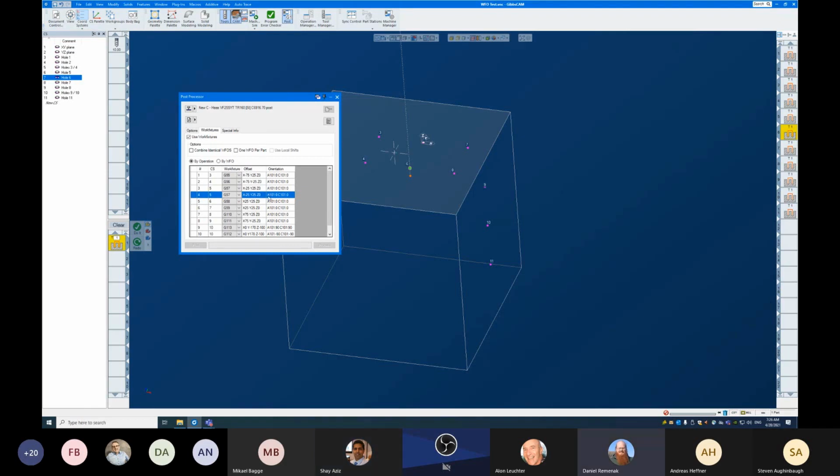You mean as far as? I would like to create a new CS, and not use it in the operation, but I would like to assign the operation to that CS. So if it's in use by a different operation, then yes, it will already have a work fixture operation. If it is in use by a part or a part instance, it is also going to get a work fixture assigned. So in this case, I can always choose to assign something back to G54.